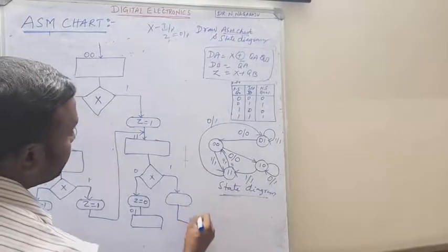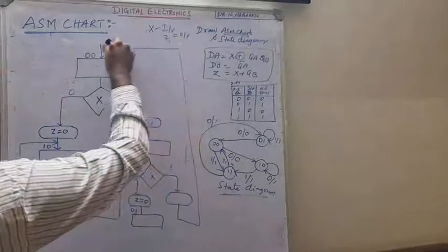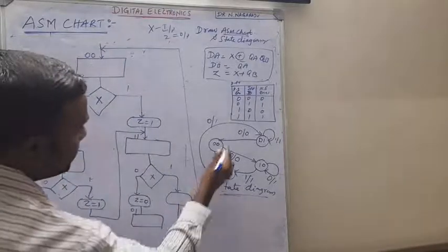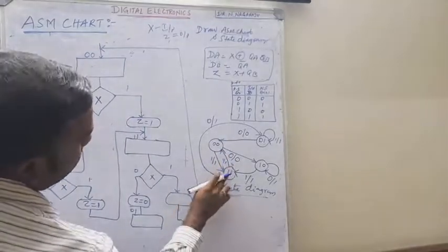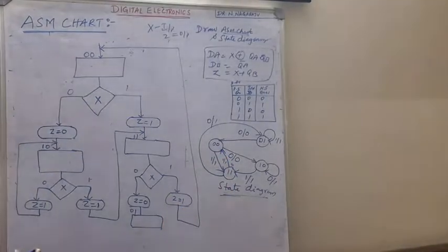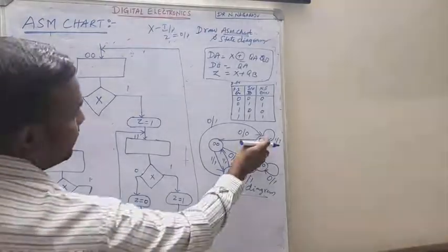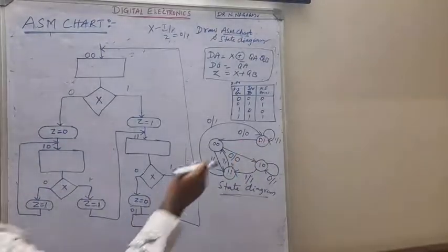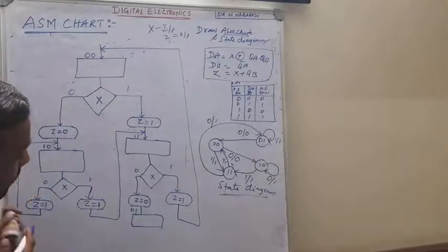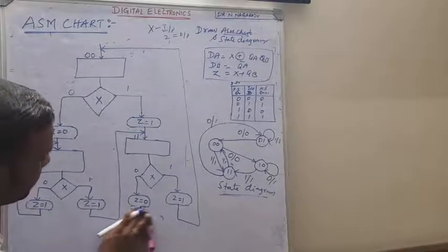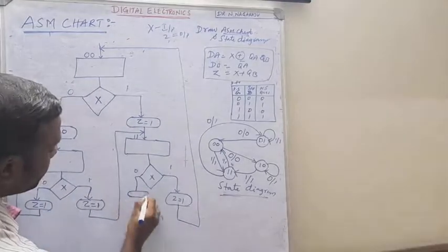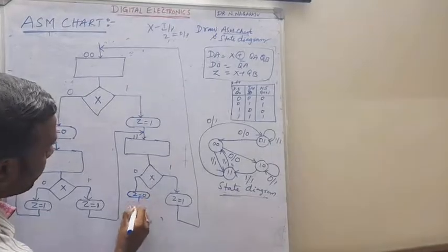Okay, so this is the input. What is the output? Here is the direction now. So Z is equal to 1, right? Next, now that is over, then come to the 0 1 state. Again one state box is there now. So first the state box, just make it like this. One decision box, a conditional box is there, Z is equal to 0, and one state box.